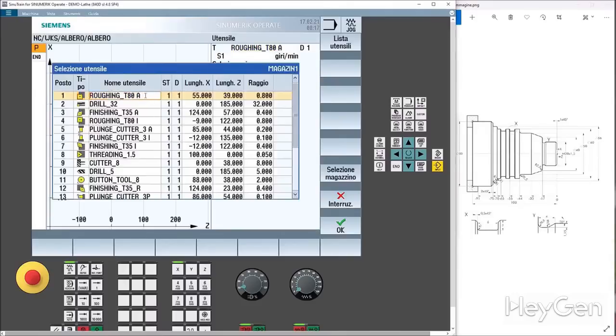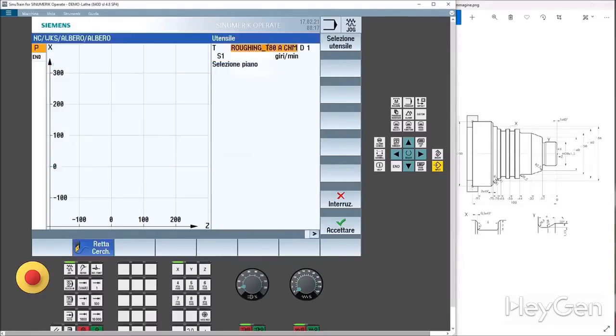Here, for example, we can write CNMG 80. By clicking OK, you can see that there's an additional comment here, but we carry it with us every time we use that particular tool. For the speed, we can set it to either RPM or meters per minute. Just click here to change the mode. Let's set it to 180 meters. And, of course, we're doing turning.